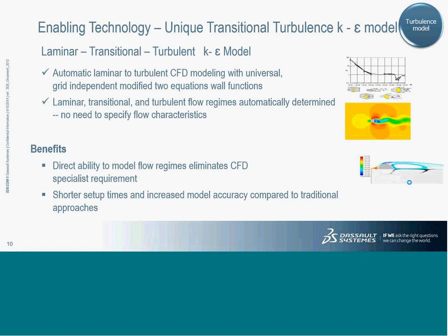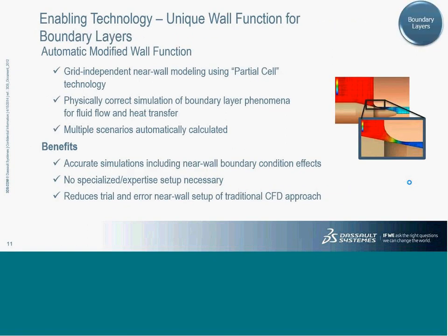And one of the interesting parts, especially for thin structures, walls, and huge velocity changes, is understanding the boundary layer, how it happens, what the velocity drop is, how quickly the boundary layer forms. And one of the challenges for a CFD analyst is to ensure that the boundary layer is captured properly. We have to ensure that the mesh is appropriate at that location. The grain of the mesh is good, and that's the only way we can ensure that the mesh looks perfect.